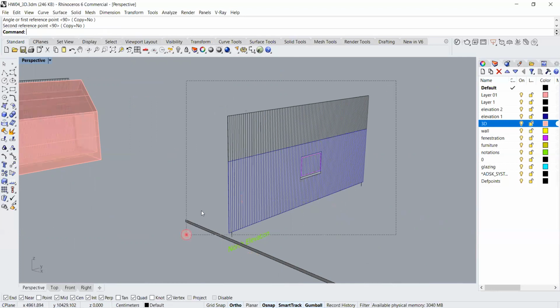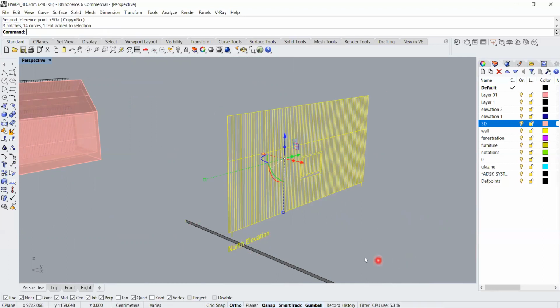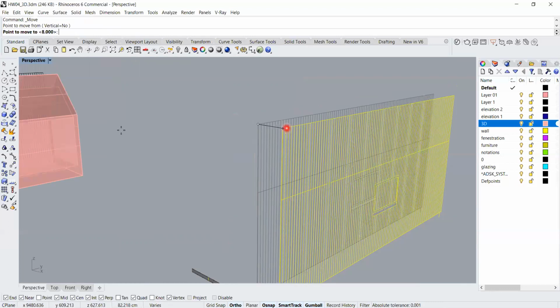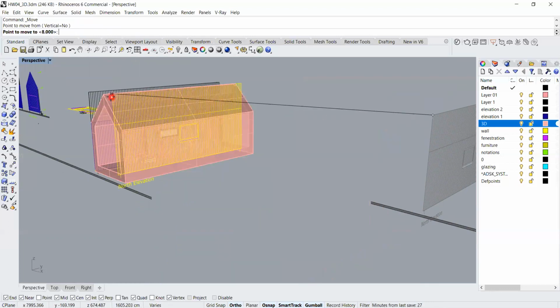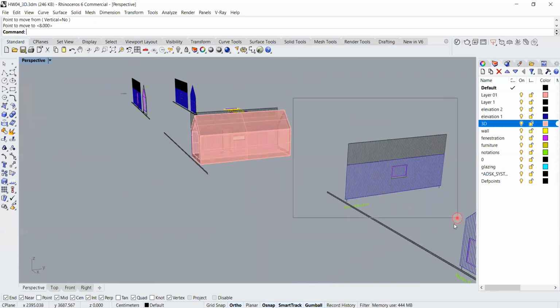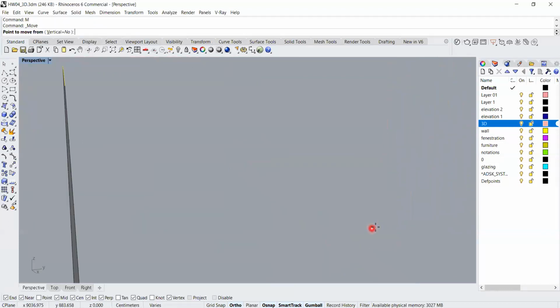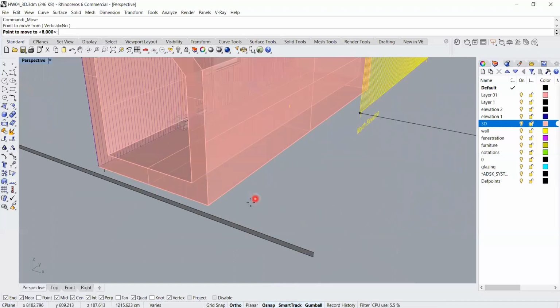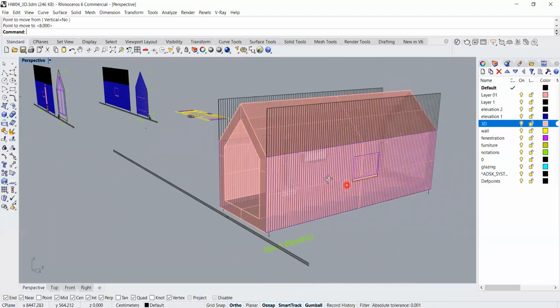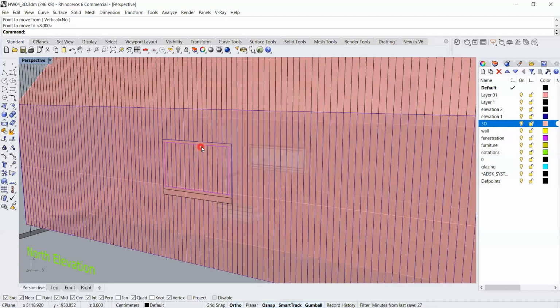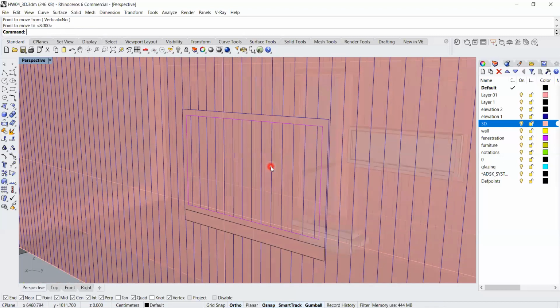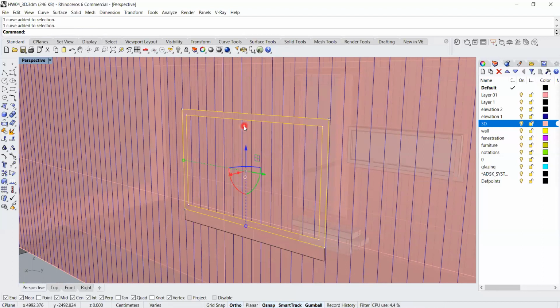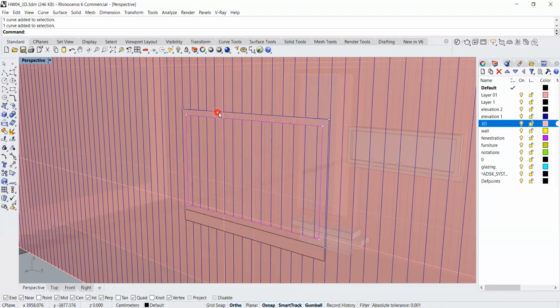And then I just select everything that I have here and move it and bring it to, of course, I should just bring it from other reference points. From here, for example, this corner. I just take it and bring it to this part. So again, I have the position of the window here. So I can just select these two curves for the frame, okay? And only this one for the Boolean. So I go for the Boolean first.